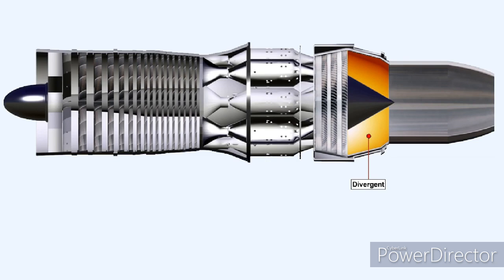This diagram shows the basic layout for the jet pipe of an aircraft without afterburners. Although the shape of the jet pipe outer casing appears to be convergent at the point where the gas leaves the turbine, the shape of the volume within the casing is in fact divergent. The divergence is made possible by the insertion of the exhaust cone, a conical-shaped device positioned close up to the rear turbine disc rear face.